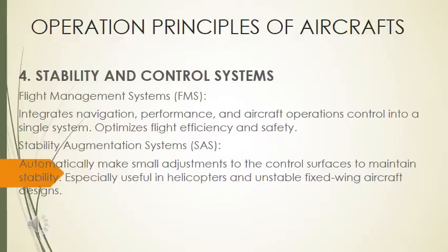It integrates navigation, performance, and aircraft operations control into a single system. It optimizes flight efficiency and safety. We also have the SAS, the stability augmentation systems. It automatically makes adjustments to the control surfaces to maintain stability, especially useful in helicopters and unstable fixed wing aircraft designs.